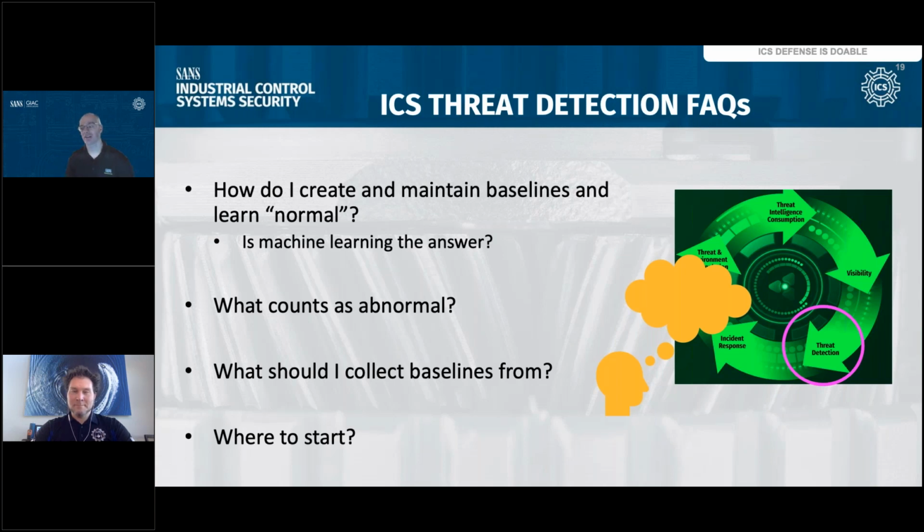Another huge one, this goes back decades for me now, is automatic config backup. And if you've got an automatic configuration backup, and we're talking all the way down to controllers at the lower levels of the Purdue model, because I got burned by an upgrade at some point where an upgrade changed a configuration in one of my devices, just the fact of the upgrade.